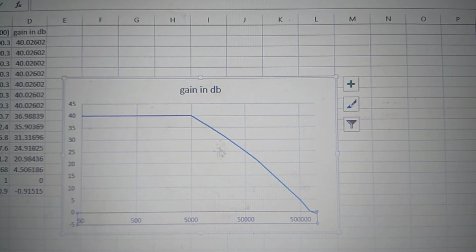Now what we are saying, for a value lower than 8.2 kilohertz, it will be like a low pass filter, and after 8.2 kilohertz it will be like an integrator, because this is the curve of 1 by s. Actually it will be integrating at around 5 times of this value. At around 5 times of this value, it will be a perfect integration. If you check around this frequency after 50,000 hertz, you will see that we are getting the integration. Now we are going to look at these 2 points on the DSO.